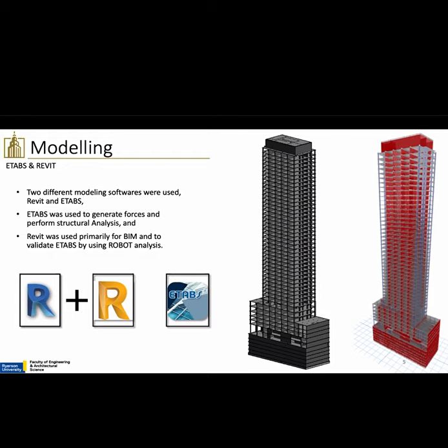However, when they were validated, we trusted ETABS more because we could consider things such as the soil springs on the foundation walls, as well as the footings. However, we use Revit for a lot of our detailing and our rebar schedules.